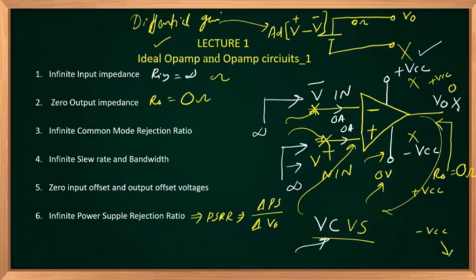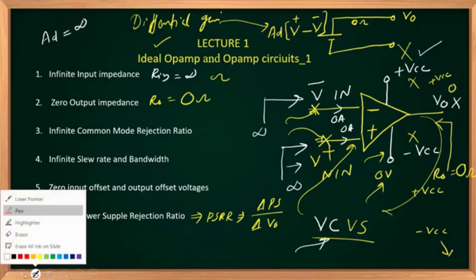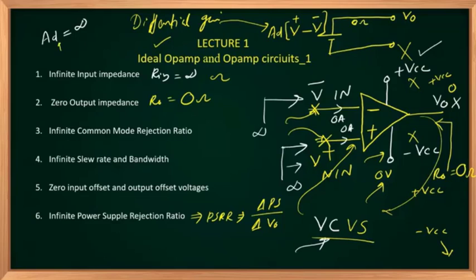So if your op-amp is an ideal one, its gain should be infinity. It will have infinite differential gain. A for gain, D for differential, voltage gain, because it is a voltage controlled voltage source: a voltage quantity at the output side, and the input also a voltage. So output by input is the gain, and that gain is called the differential gain. And what about the common mode gain, AC? Ideally...